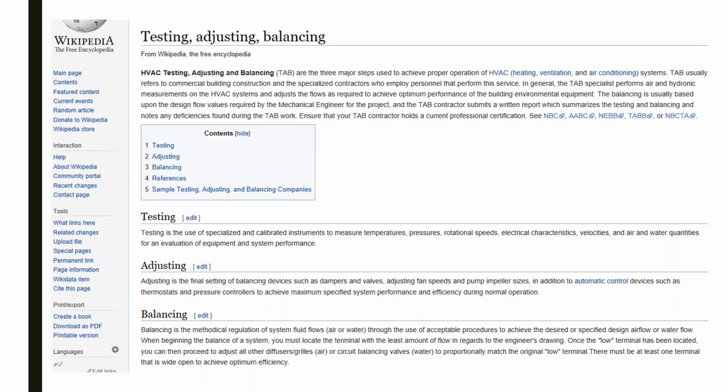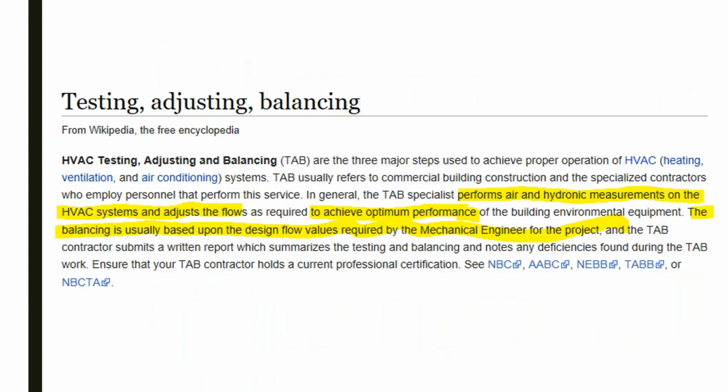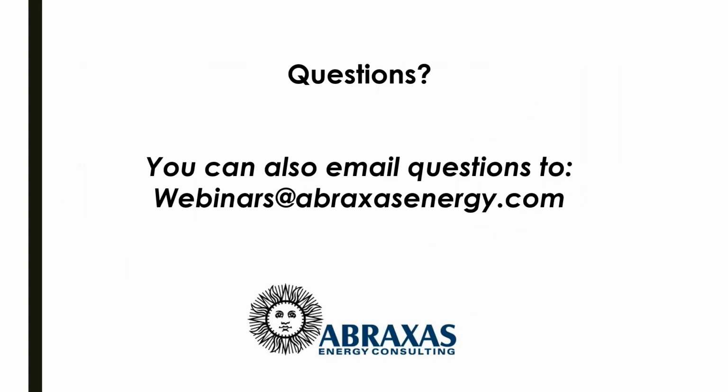But issues like this, out of calibration thermostats, that could be part of the problem. Failed controls on the VAV box. But when you replace it, you have to set it back to a test and balance level from either the original design, or you come up with your own square foot CFM, things like this. But that's small compared to the entire building. So I'm not saying that you have to retab the entire building, but you're going to focus on where you need that effort. So that cuts down your cost for test and balance. You know, you have to be smart and manage your project.